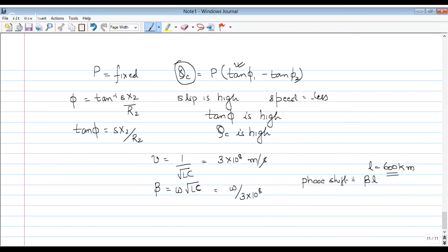I have answered this. In a second order RLC circuit, which peaks faster, underdamped or overdamped? The underdamped is the fastest system, so it will peak faster as compared to critically damped or overdamped. And anyways, there is no peak observed in critically damped and overdamped response because they can never exceed the steady state value. So peak is only observed in an underdamped system.